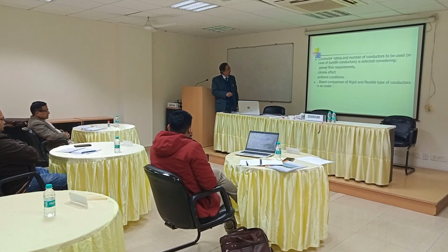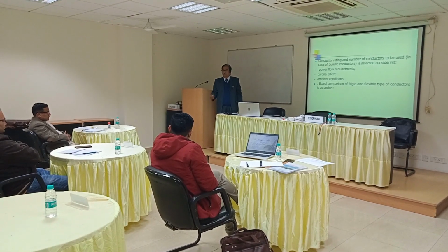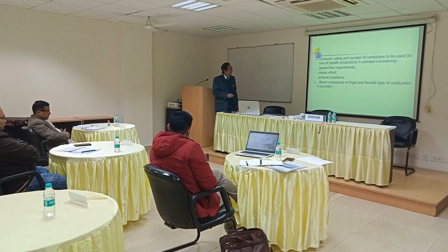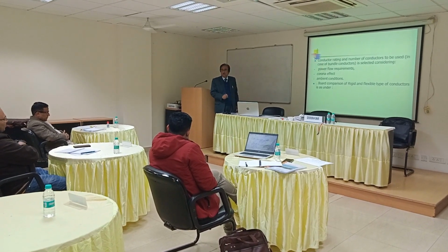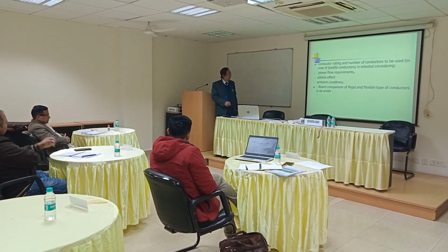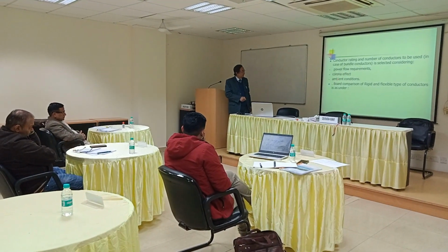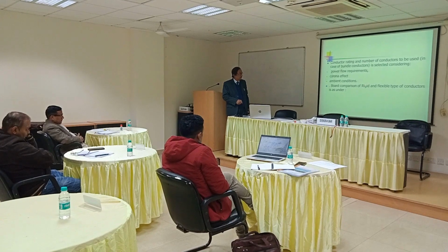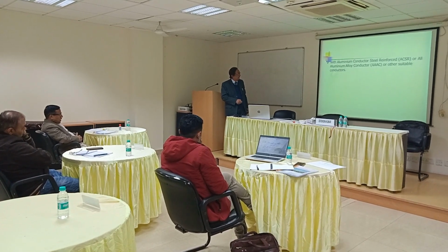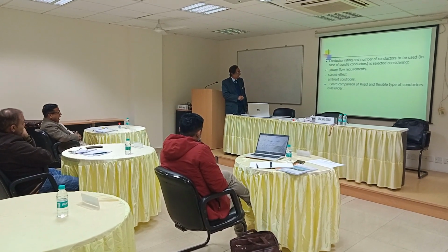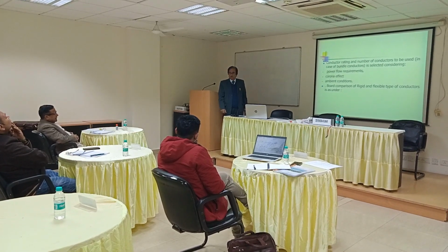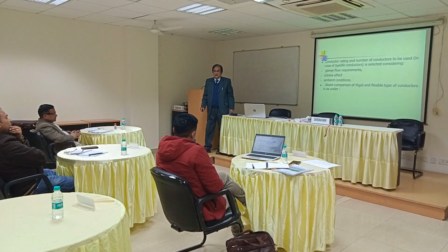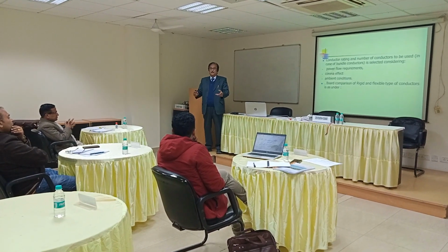Now, conductor rating: what shall be the conductor rating, and how many conductors in one particular phase, will be decided depending upon the power flow requirements (how much power we are to carry), corona effect, and ambient conditions. These are the three factors. Power flow requirements means we have to select the conductor according to how much current we want to carry.